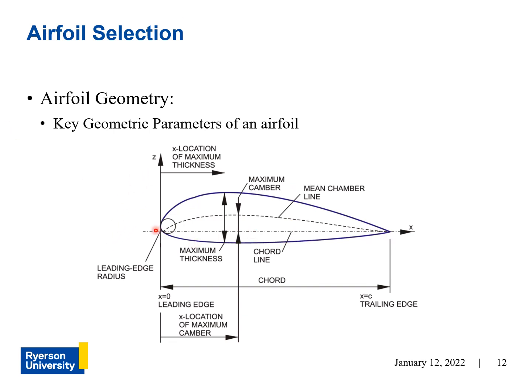So to rehash, in terms of the camber, it affects the lift-induced drag and the aerodynamic pitching moment, as well as the lift, and the thickness affects or is more relevant towards the skin friction drag. So those are the two parameters and the effects they have on the aerodynamics of this airfoil.